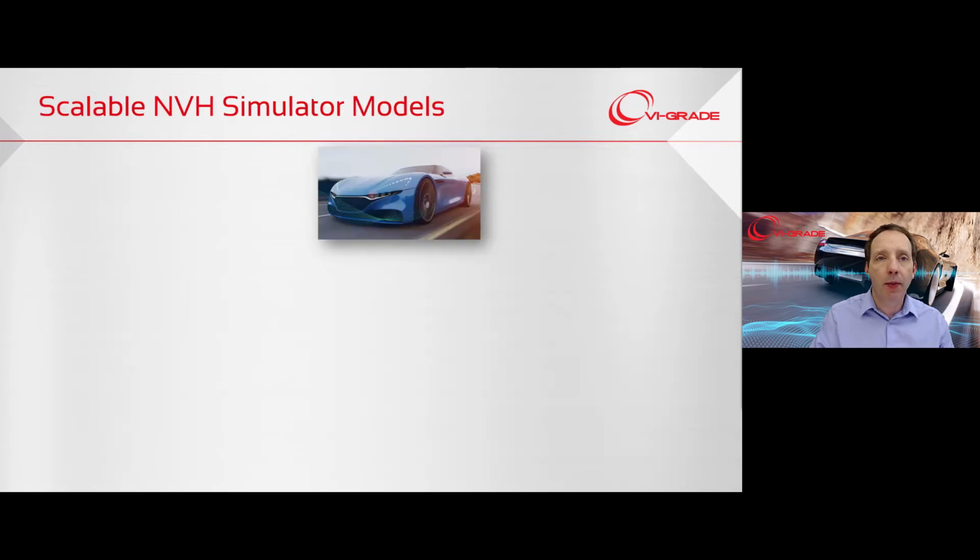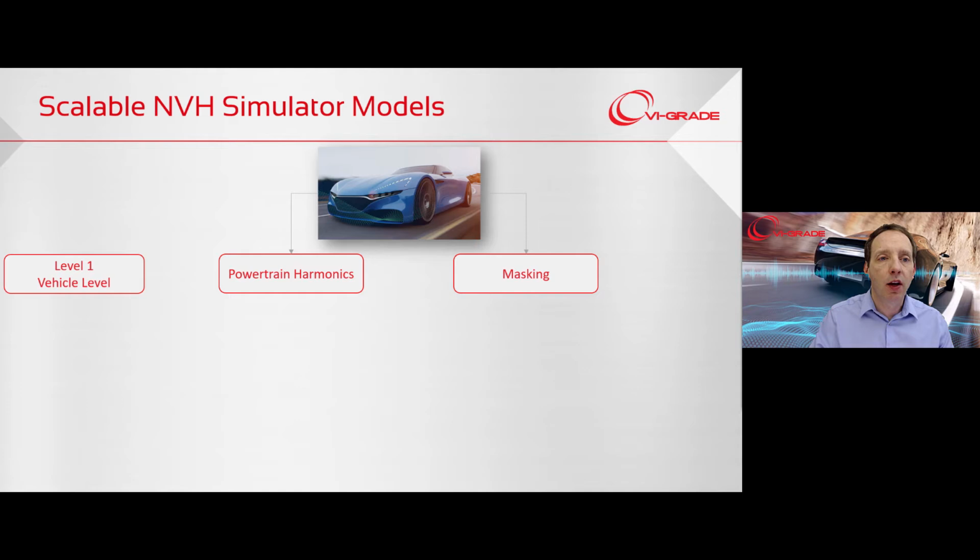One of the questions I'm asked a lot is, how much data do I need to make an NVH simulator model? Well, it all depends on what the model will be used for, how much accuracy, and how much detail is required. Simple level 1 models are very useful for benchmarking and high-level target setting and require very little time and data to create. In fact, you can create a simple level 1 model that is completely functional for driver-in-the-loop interactive simulation from a single recording.